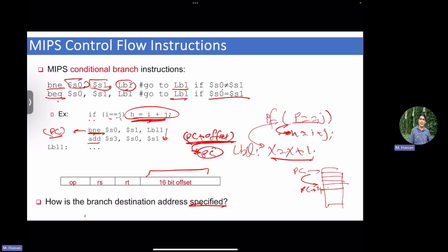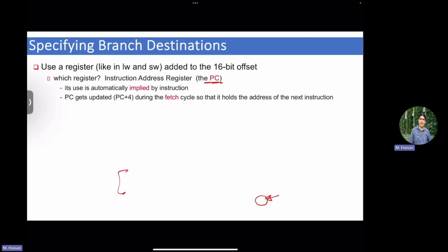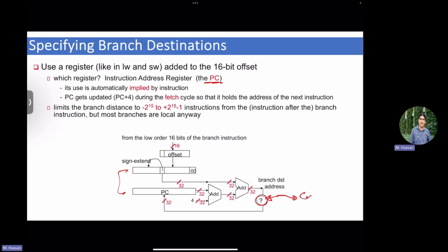So if you have a conditional branch, there are 2 possibilities. I either jump or I don't jump. Based on what? Based on your condition. If you have a BNE instruction like here, you take the 2 registers, compare them. If they are not equal, I jump. If they're equal, I don't jump. Right? It's quite simple. So this is why we have a question mark in our figure here. We say, well, in reality, I need the condition result. If the condition is true, I update the program counter. If the condition is not true, I have to increase the program counter only by 4. Good.